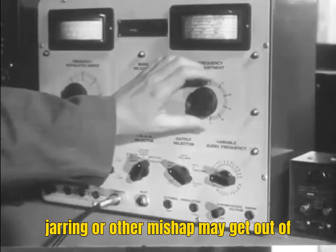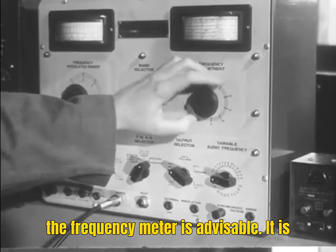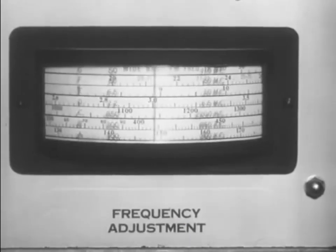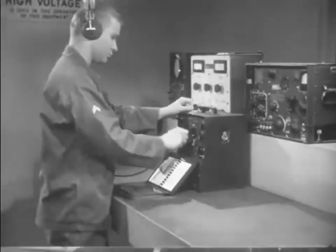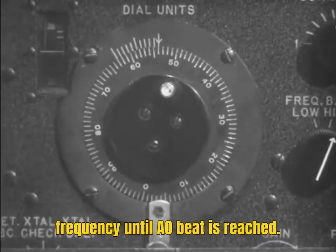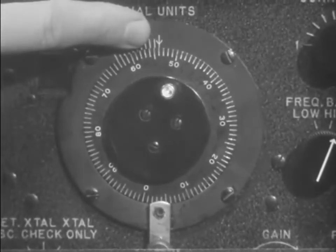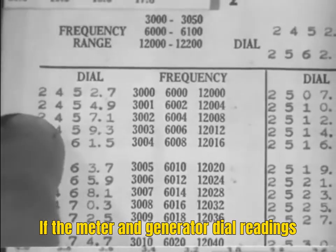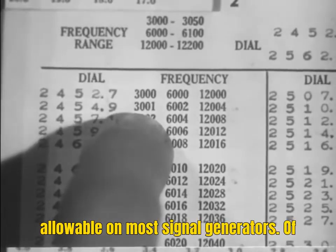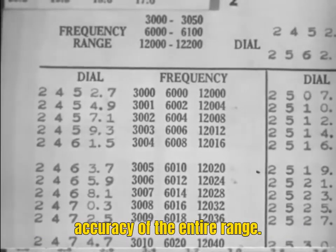The signal generator, through jarring or other mishap, may get out of alignment. A frequent check of the calibration of the signal generator with the frequency meter is advisable. It is only a matter of sending out a signal on the generator which is received by the meter. The frequency meter is tuned to the exact frequency until a zero beat is reached. If the meter and generator dial readings agree, the generator is in tune. A tolerance of 1 or 2% is allowable on most signal generators. Of course, this procedure must be accomplished on each band to check the accuracy of the entire range.